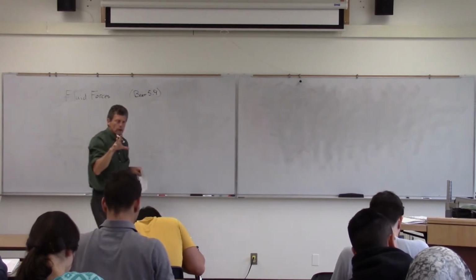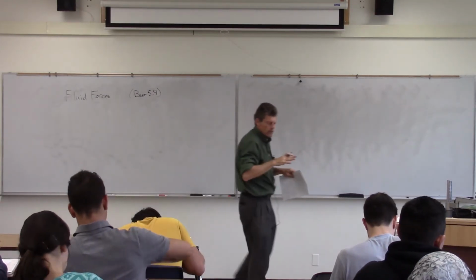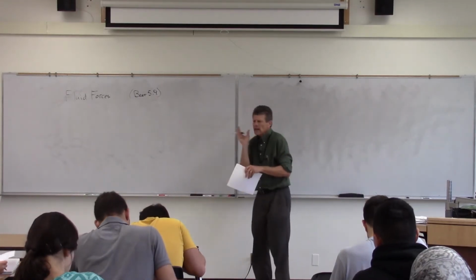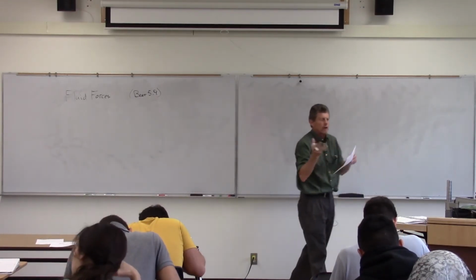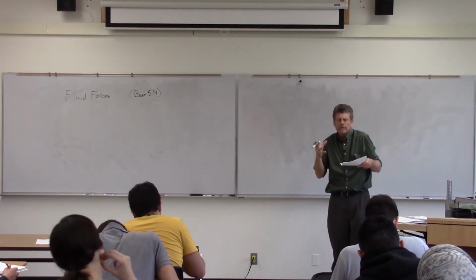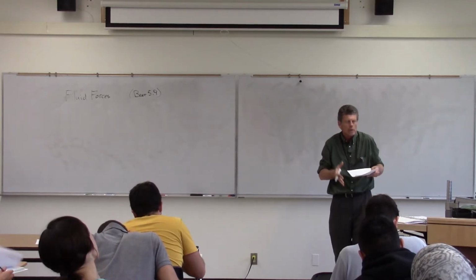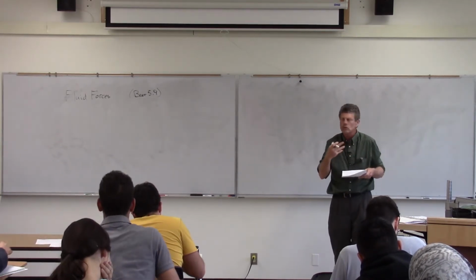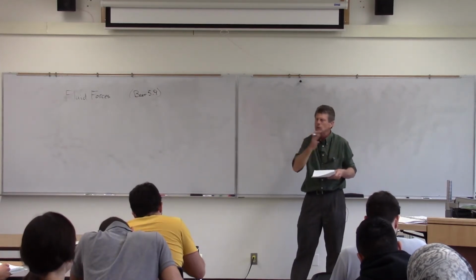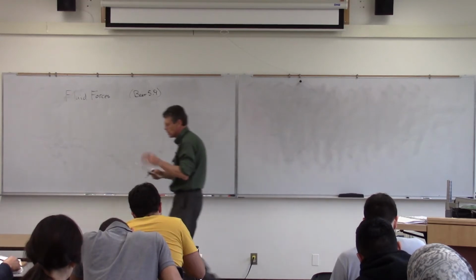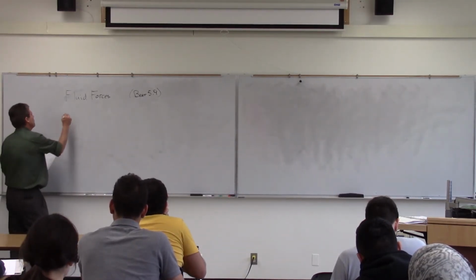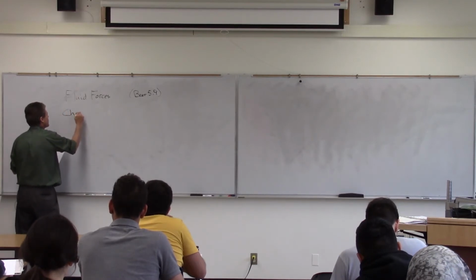Okay, the next thing we're going to do is then go beyond that a little bit further, and we're going to start looking at fluid forces, again, which is something we're going to have to deal with. And where we're going with this is we've got fluids acting on a wall or a floor or something like that. We need to find that equivalent force and location of that force to be able to use our statics equations. So we're going to be basically doing the same sort of thing. Let's find the location of that particular equivalent load. Now, fluids are a little messier, however, and we'll talk about that.